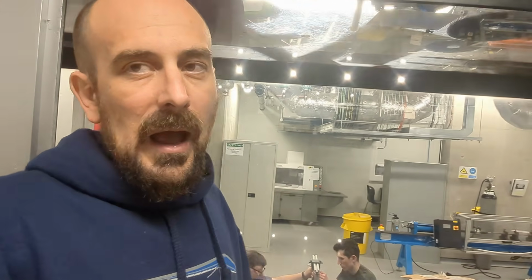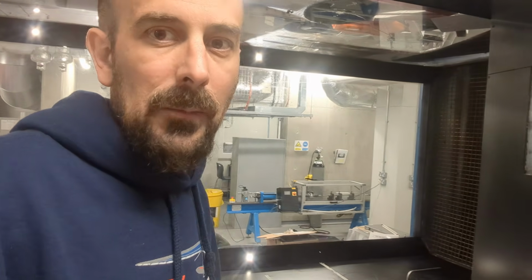Obviously for what we're doing at the moment, we're only really interested in drag, so we're only really caring about the force in the flow direction. Obviously it's not really generating any lift, there's not any sideways force on it, and we don't really care about the moments either for this purpose. What you can also see there is a pitot tube, so that's measuring the speed in the tunnel, so that we have the actual airspeed for each condition we're running.